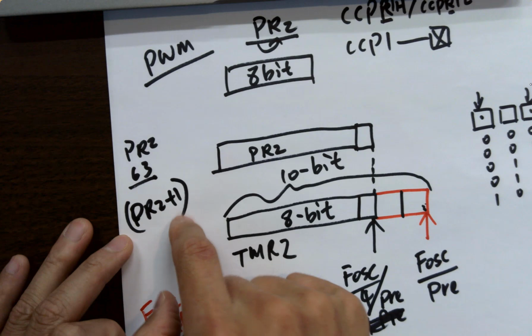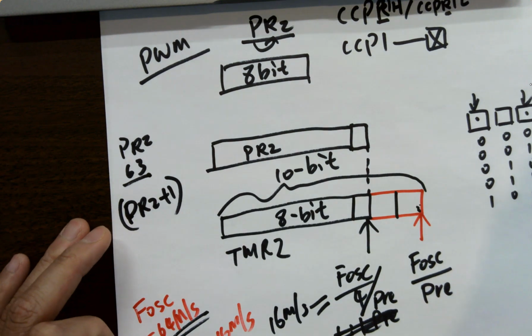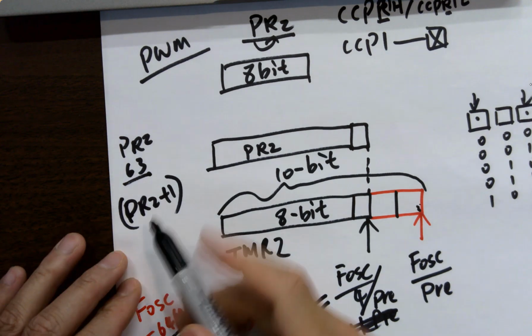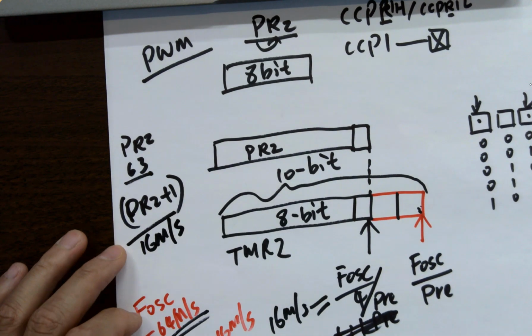How long does it take? That over 16 mega. Divided by what? If you are given a count to find out the time, that's just one of the two problems we have been dealing with all the time. If you are given the count, divided by what? Divided by the frequency, right? So you flip that to get the time.